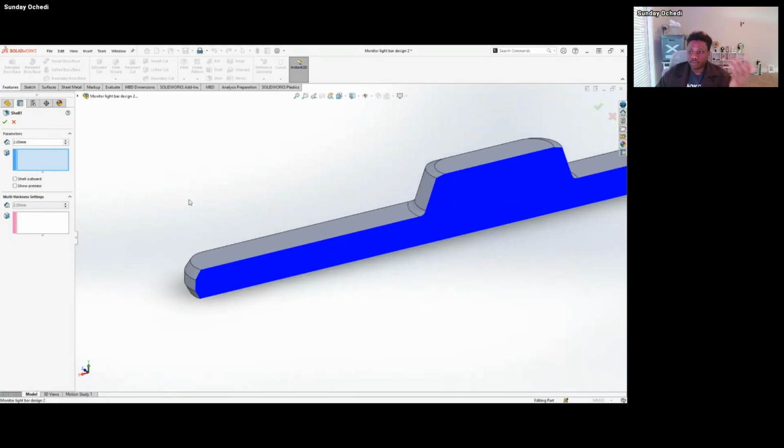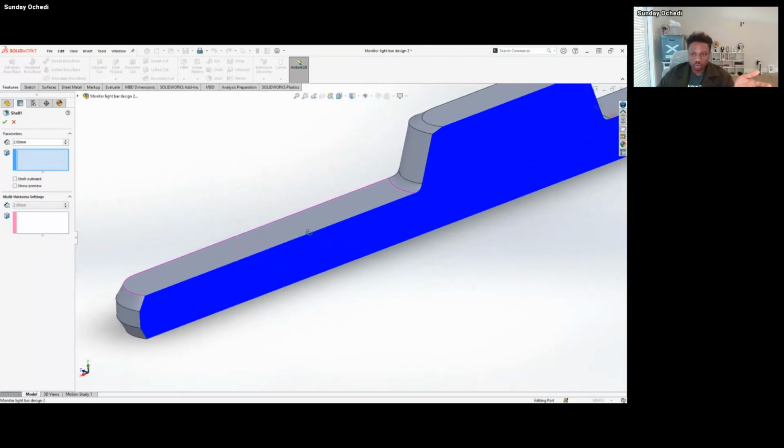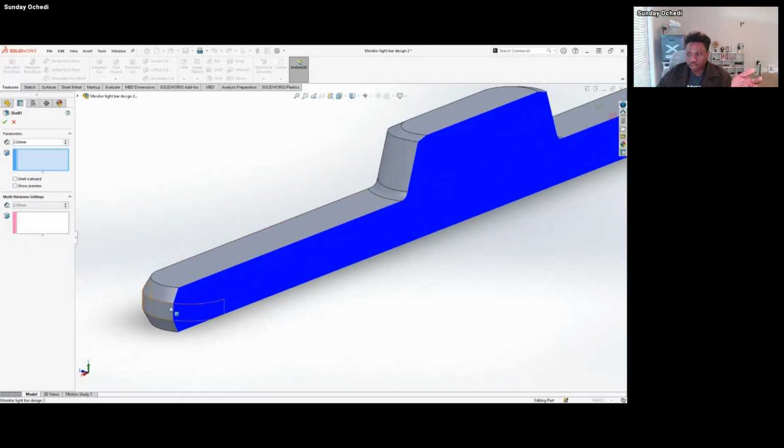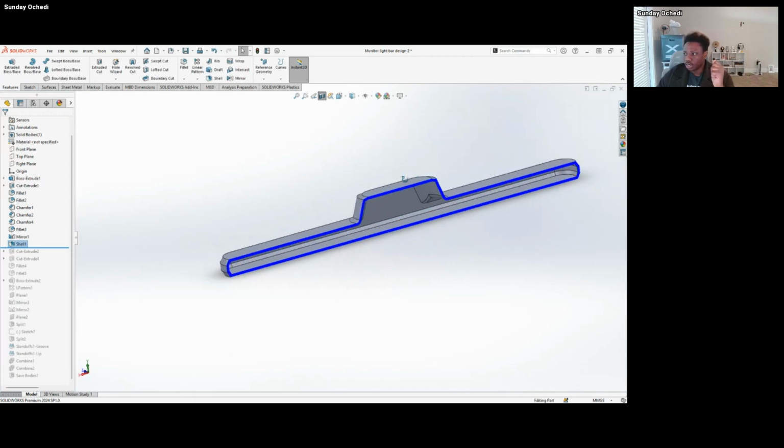And if so, you have to understand the use space and basically what you want to use it for. If you want the thickness to be outward, so you add an extra layer, or you want to maintain the dimension you already have, then you shell it inwards, which is already what you have here. So once you shell, this is what you have.